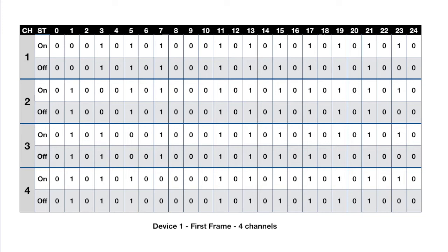And we see now that actually the first part of the signal, the one which was in green before, is changing with respect to the channel that has been selected. So if we compare, for example, channel 1 to channel 2, we have that bit 1 and 2, 1 and 3 are changing. So like we have seen for the choice of the device itself, a 0 here indicates that the channel has been selected.